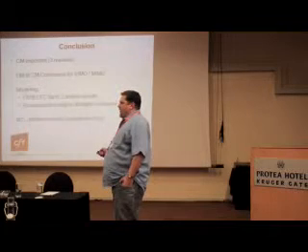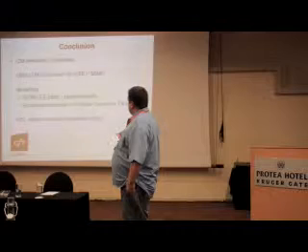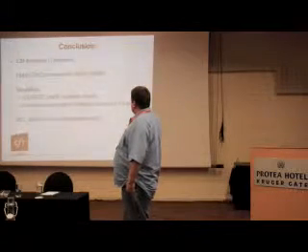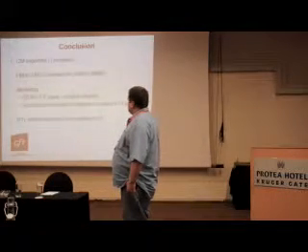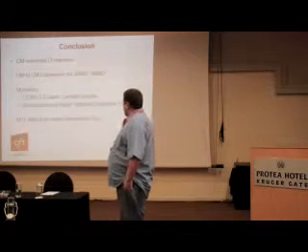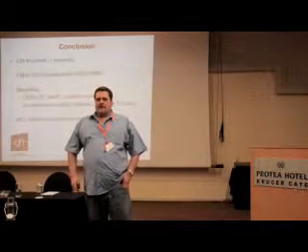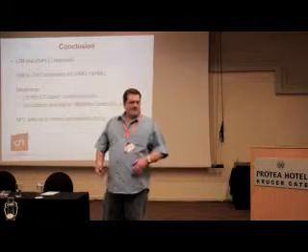If we want to model common mode in the Cenelec band, we can use lumped circuit theory. In the broadband, we can use multiple conductor transmission lines. And in the end, multi-conductor transmission lines are difficult to model because their parameters are all functions of frequency. Thank you.